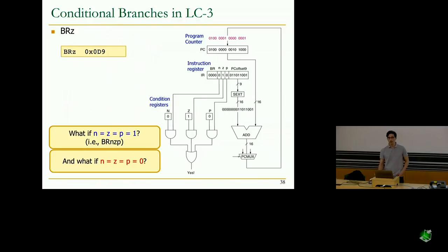There's no branch, right? No, the branch will never be taken. We will simply go to the next instruction. And actually, we are going to waste some cycles because we could be reading and executing some instruction that in the end does nothing because it doesn't even evaluate any condition codes. But although you might think that this is useless, this is useful in some particular machines. And probably we will talk about this when we study pipelining.